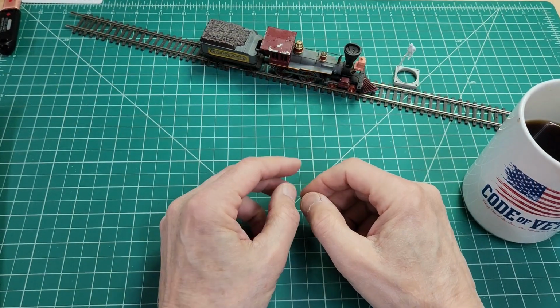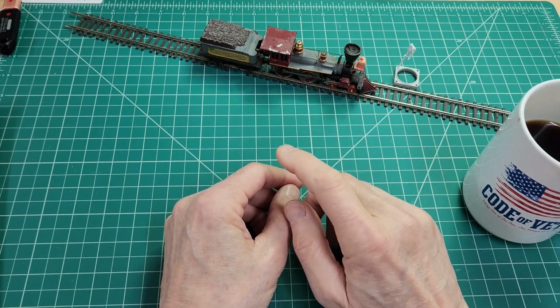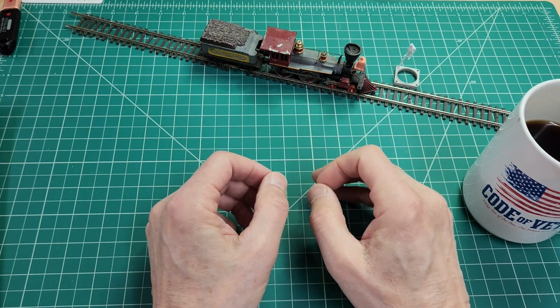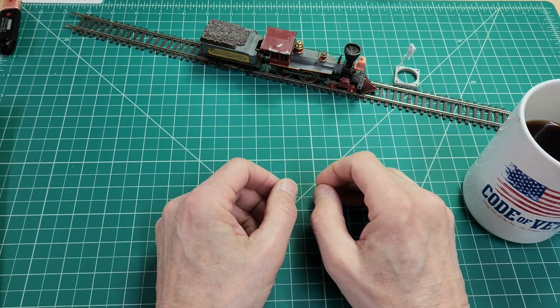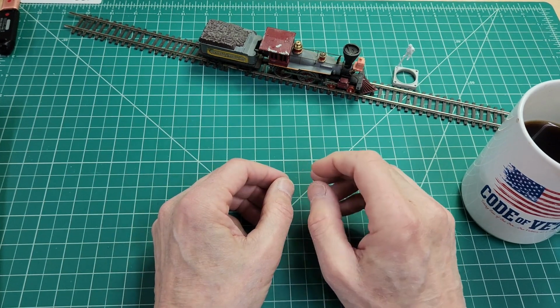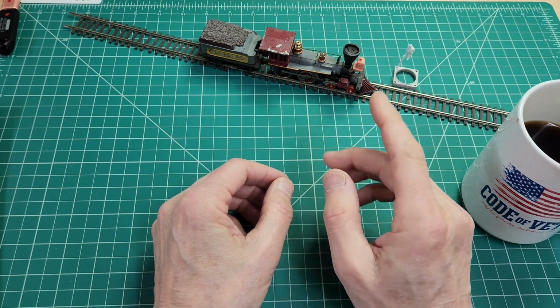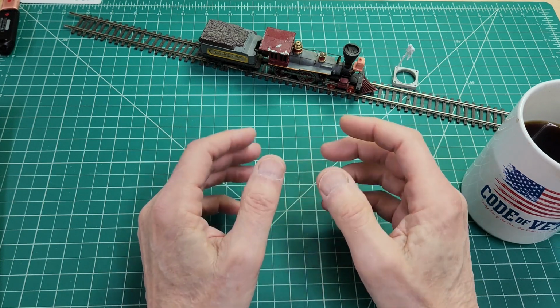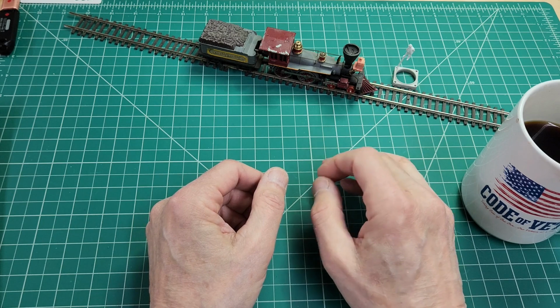In the previous video, which was episode 23, I discussed the host shield library's task method as it pertains to the startup function that detects when a device becomes attached. I also discussed the task's state-wise progression as the library code configures itself for that attached device.